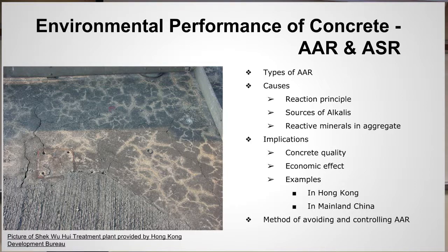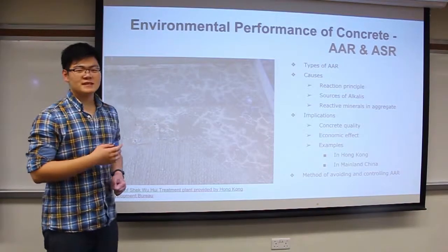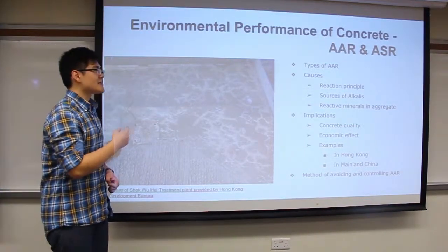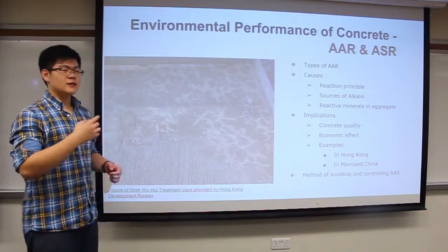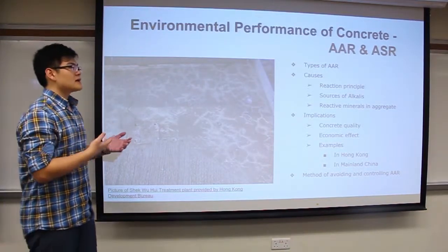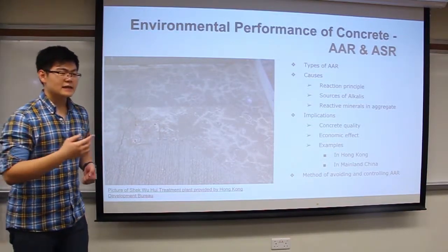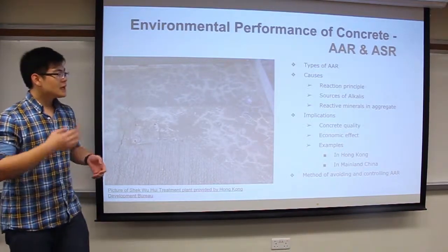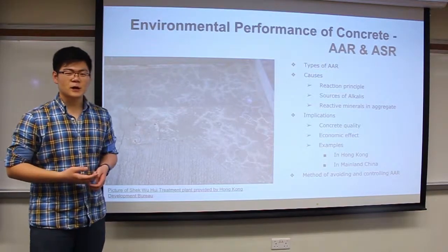Thank you, Richard. Next, I will talk about the environmental performance of concrete with focus on alkali aggregate reaction and alkali silica reaction. Alkali aggregate reaction is a reaction between alkaline content and reactive minerals in aggregate in concrete when moisture content is present. And AAR will negatively influence the performance of concrete.